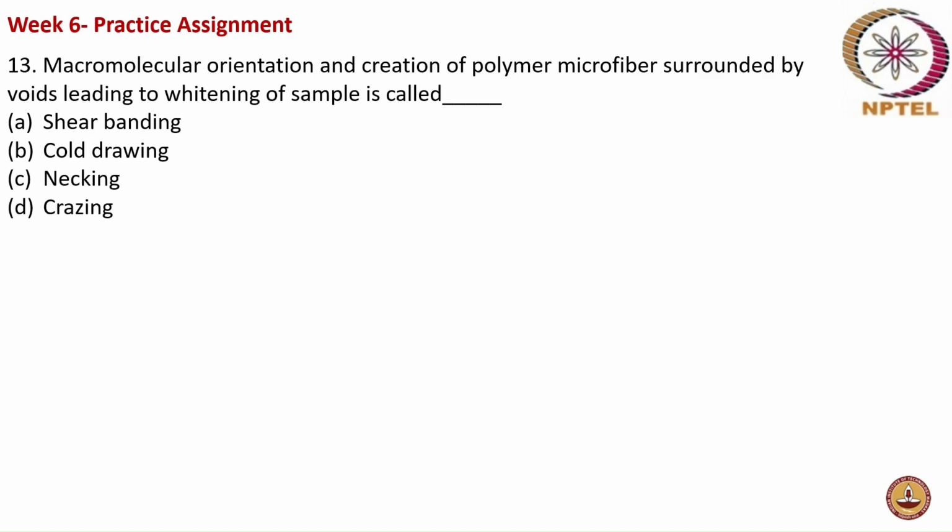Next is macromolecular orientation and creation of polymer microfibers surrounded by voids leading to whitening of the sample. Is it called shear banding, or is it called cold drawing, or is it necking or crazing? Option B, cold drawing. Cold drawing, you're saying. Is it so?